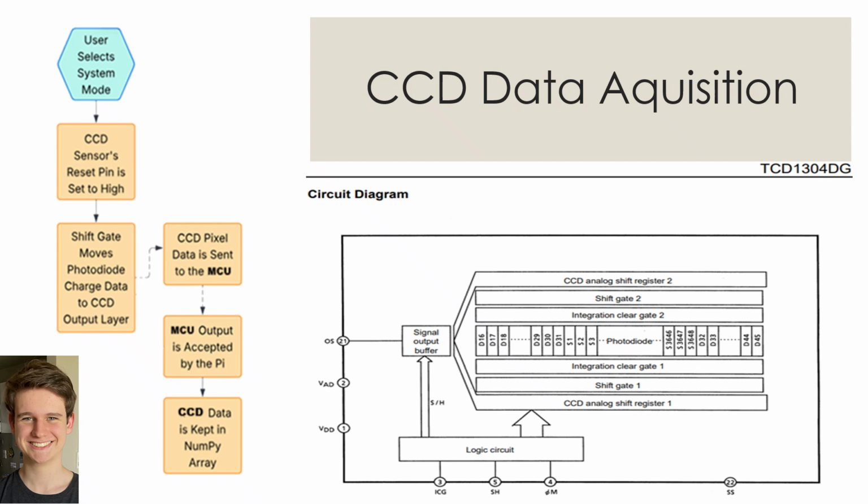By setting the frequency and duty cycle of each signal, the output of the CCD is coordinated with the sampling rate by the ESP32. This way, the MCU receives the analog voltage output from the sensor and converts it into an integer array using the controller's embedded analog-to-digital converter.